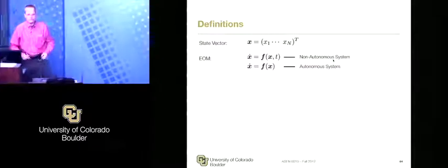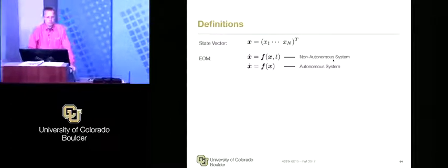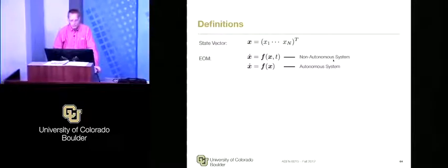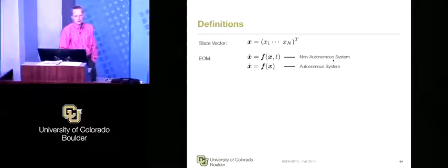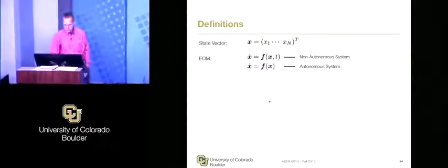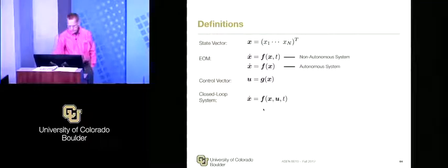Is there a better way to normalize the quaternions than just dividing the newly computed quaternion by its norm? That's typically the way I've seen it done. Yeah. If you have a DCM, there's some nearest orthogonal matrix stuff that you can look up. With the quaternions, basically, it's a very small value. You just renormalize it to keep it bounded. Which is an error source, of course, but still, everything has error sources.